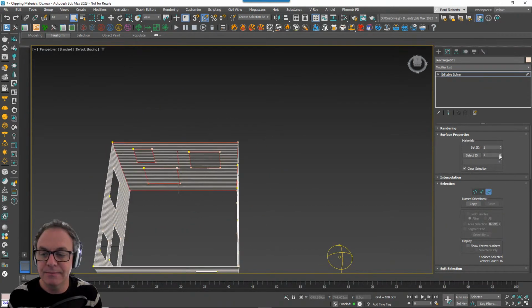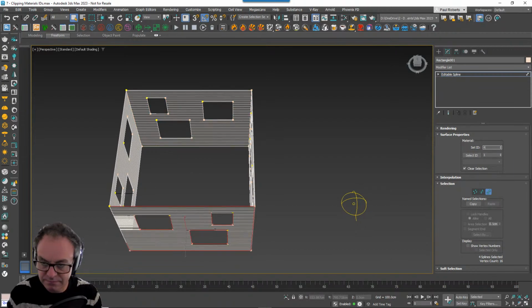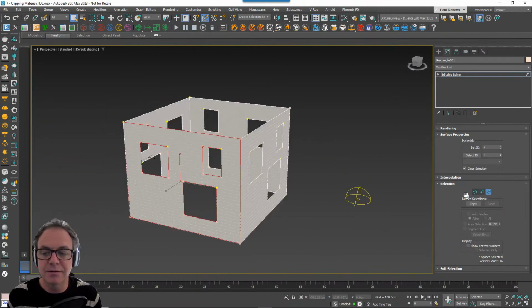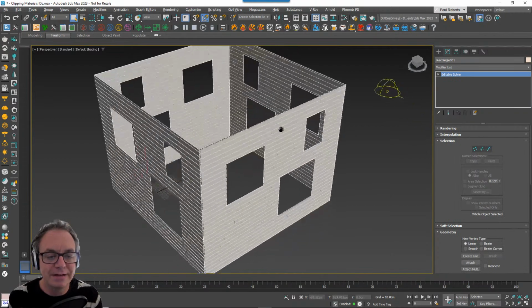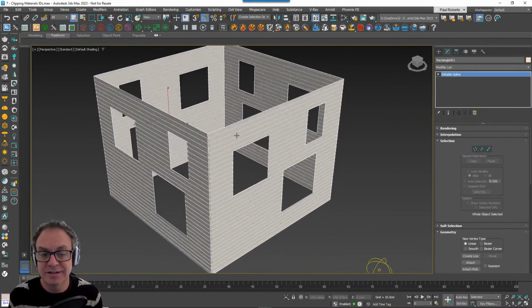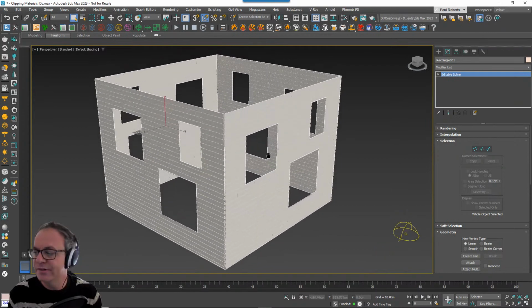You can do the same here. Give it a different value. And this one finally. And you see that fixed it instantly. So it's very easy to do, but maybe not many people are aware that it's there or how it works. But that's basically it. Just group together your splines using material IDs and use that third mode in RailClone if you're using clipping areas. Okay, so that was a nice easy one, I hope.